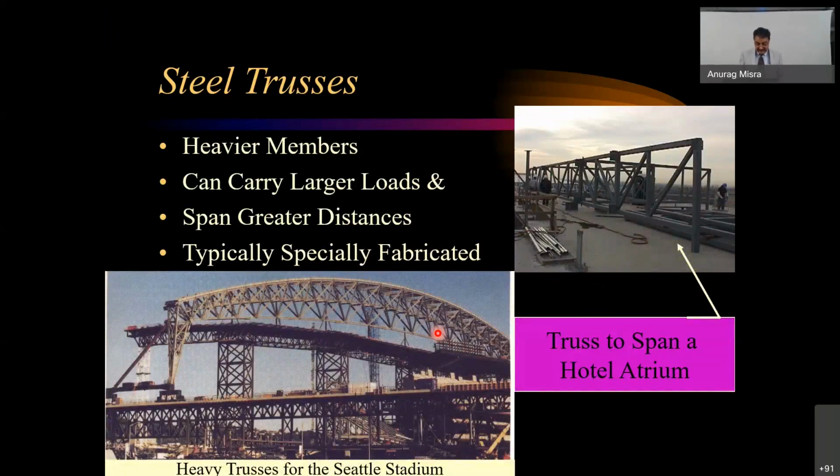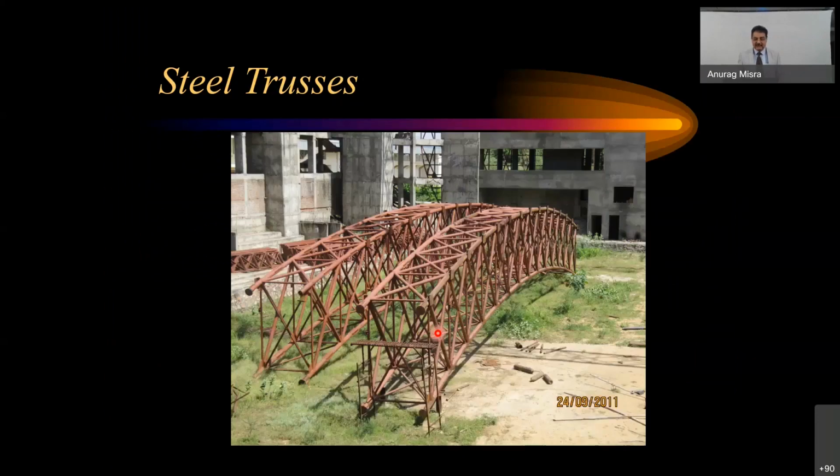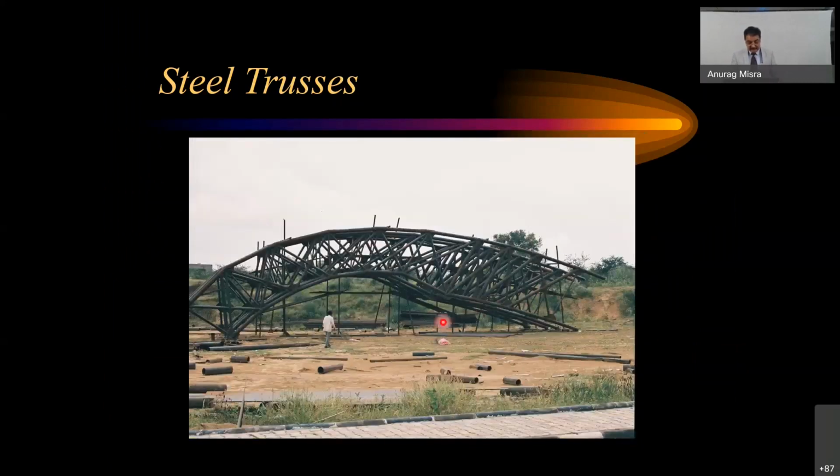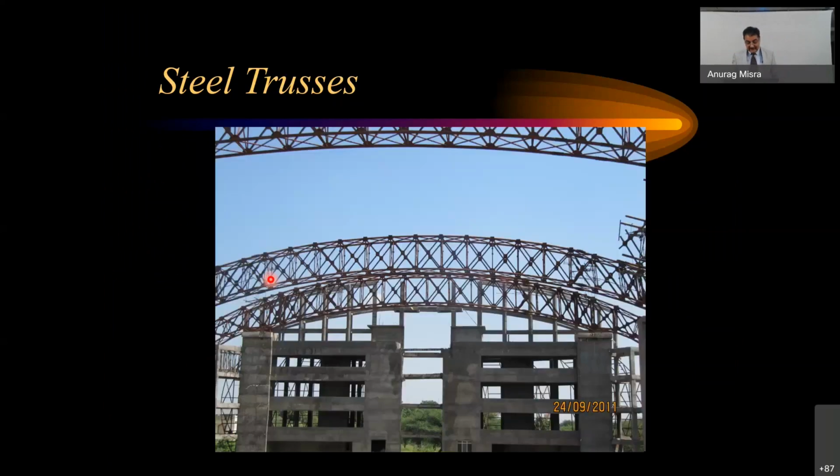These are all open truss examples, where you could use them for longer spans. Some of them, again, are created in pieces. These are all stadium cases where you could actually go for these kinds of components, bring them together, and do the site welding. Here, some site welding, or you can design a connection which is just bolted ones, and you can deal with the huge spans this way.